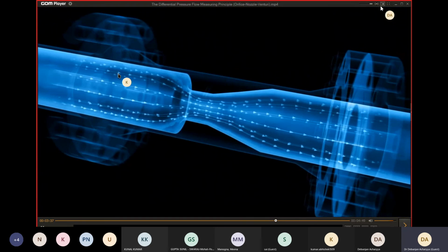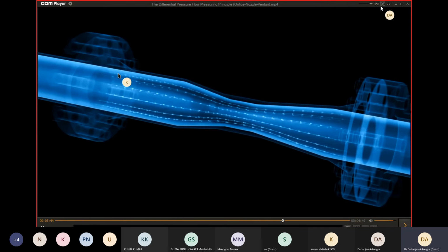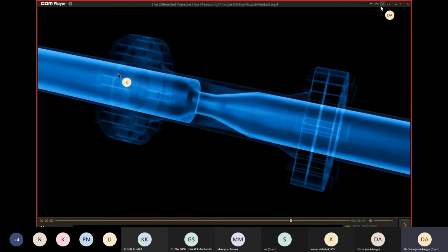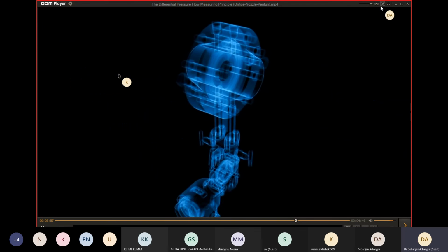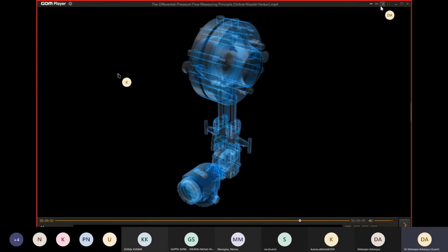Turbulence reduction is even greater with Venturi nozzles. And finally with Venturi tubes, where the restriction is created by longer conical constrictions in the pipe wall. All these designs can be supplied with different restriction diameter sizes, so that the pressure loss and the differential pressure generated can be optimized for the process conditions.